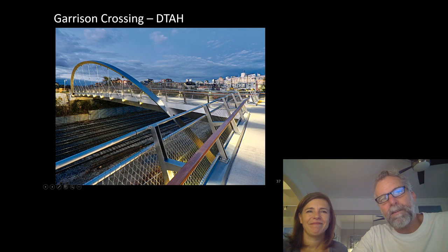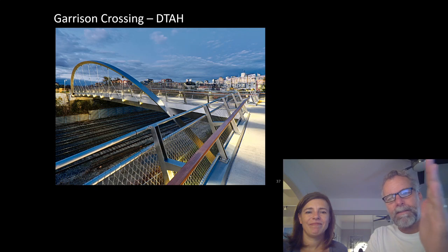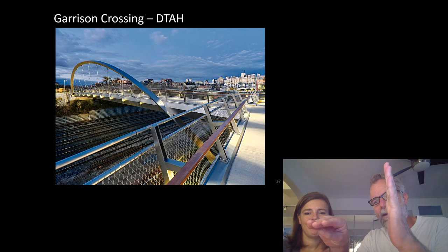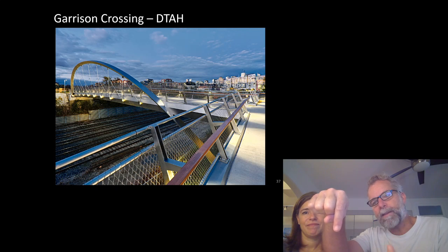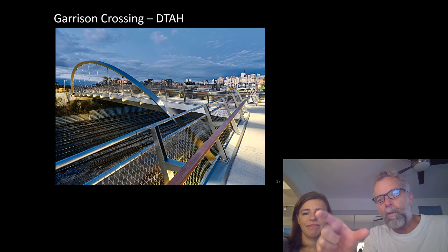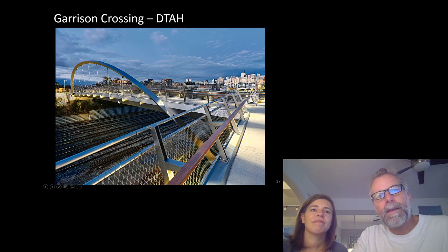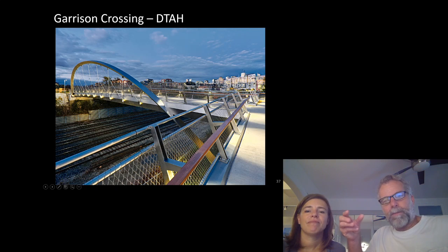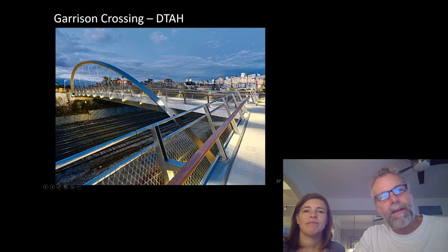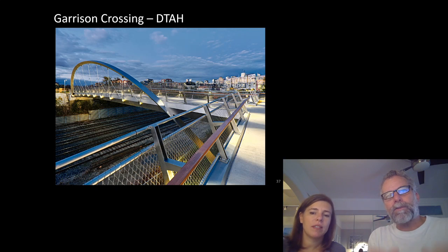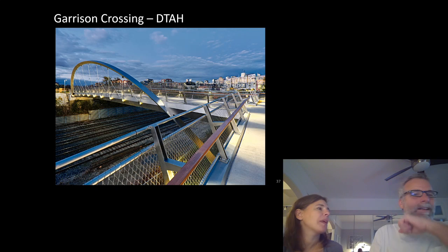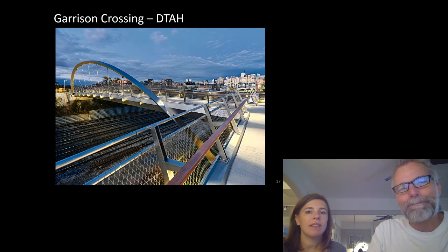This is a straight bridge with a single-sided arch. The interesting thing about that is that we've got the single-sided arch, and on this side we have our deck. Our load is out here. Our resistance is here. Our load is in the middle of the deck. Our resistance is in the arch. So the whole thing wants to twist. The torsion, so the bridge deck itself is twisting like a shaft. That torsion is coming out into the abutments, and the bridge itself has to be made torsionally rigid. So the bridge is a big box in order to give it torsion, or solid cast concrete where the reinforcing is doing that, but those are the options.